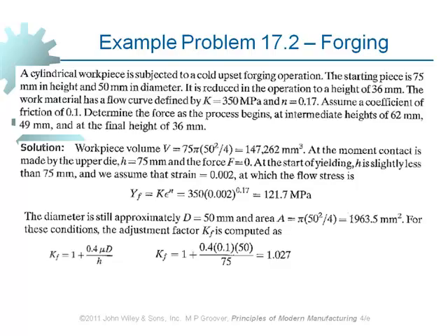I was just wondering, if n is 0, meaning it's a high temperature operation, is it okay to say that... Then you put 0, and you get 1 for this. If this is at elevated temperature, n is 0 and this becomes 1. So it's okay to assume that Y is... Yeah, if this is above the recrystallization temperature, then n is 0, and you get YF equal to whatever K is. Yeah, that's right. KF is computed, YF is computed.